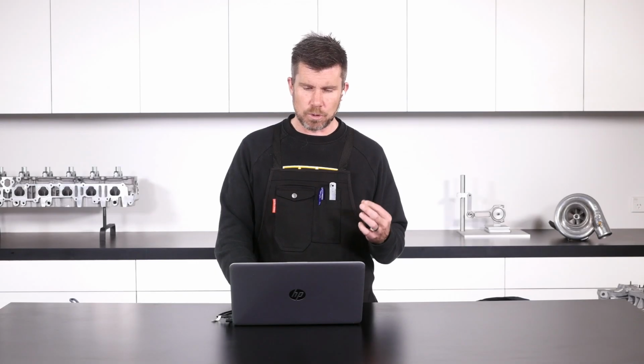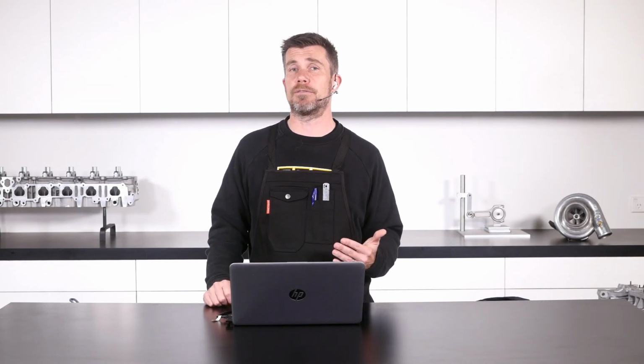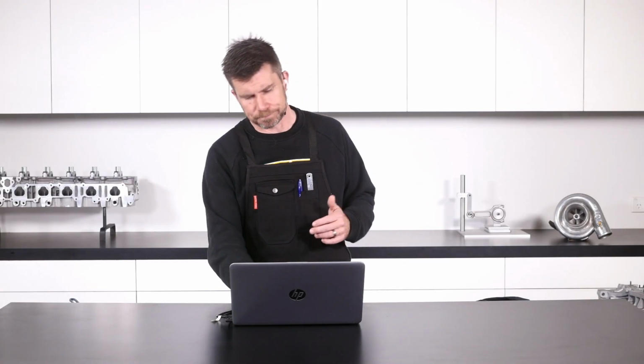At this point, I'm aware of obviously the Haltech Elite range of ECUs offering engine pressure ratio. The Adaptronic also offer this. In fact, they make it nice and easy because they have a built-in exhaust manifold pressure sensor straight on the ECU case with their modular series. There are a few others that I am struggling to think of, but it isn't particularly common. So what I would say is, if you are thinking that this sounds like something that you might be interested in pursuing, just don't expect that every ECU brand that you're dealing with does have this covered. If you do want to use it, make sure that you check out that that is a possibility.